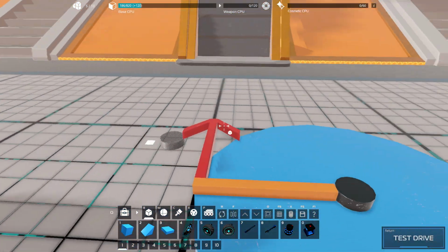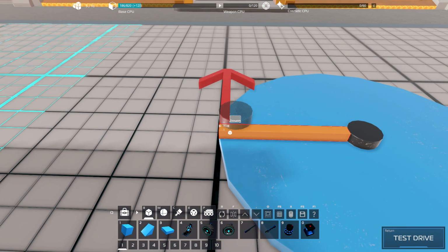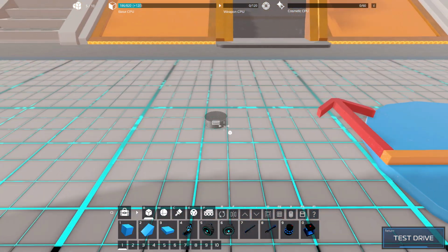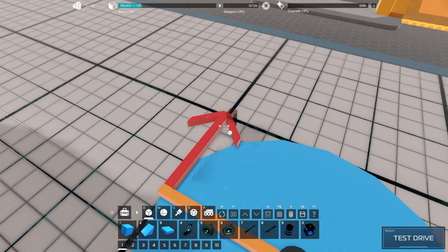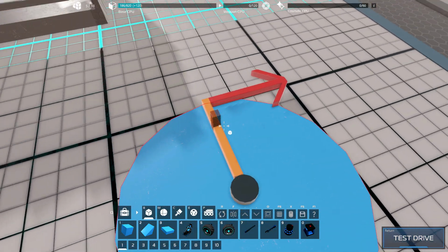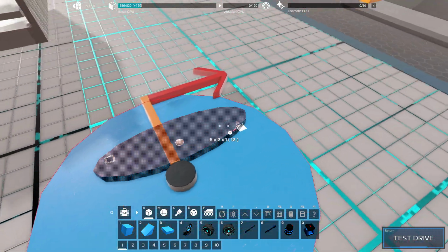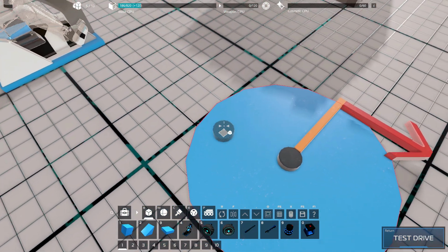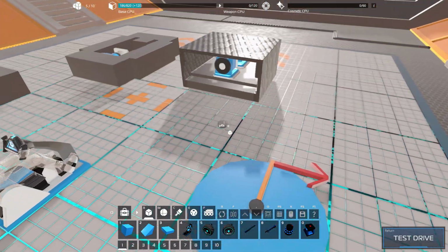So if I had two thrusters pointing this direction at this distance from the center, it would be a moment of 2. If I increased their distance from the point of rotation by twice this length, it would be 4. And so on and so forth, right? And you can pick any point of reference and do that same calculation using that point of reference of rotation. So you can balance moments around any point.